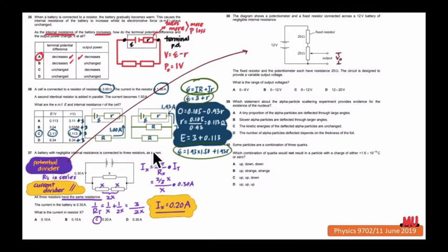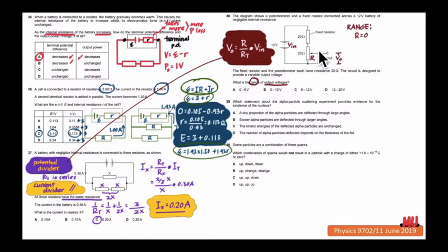This is the output voltage, input voltage. This is the resistance of the component from which we want to find the voltage across. Alright, R. The formula is V sub O equals that resistance R over the total resistance in series times the input voltage. Now, for the range of possible output voltages, those can be determined by considering R equal to 0 up to the R equal to 20, minimum resistance and the maximum resistance.